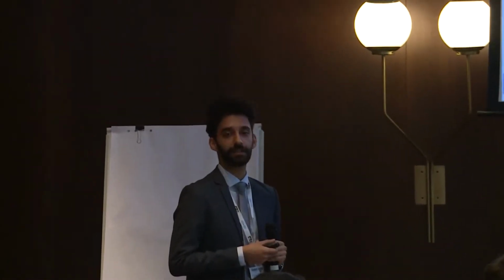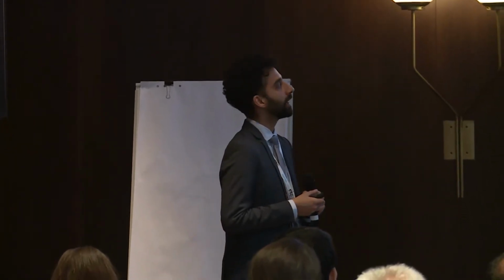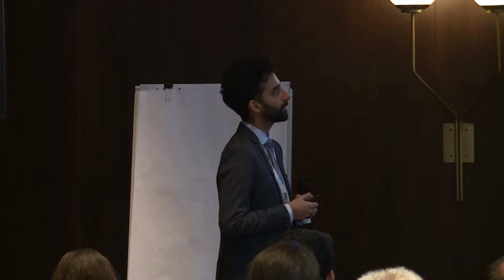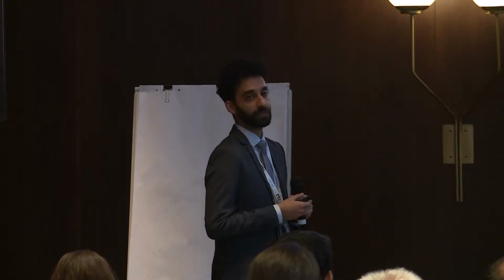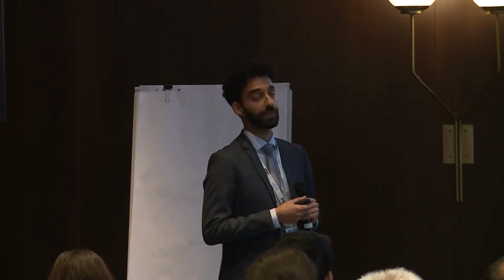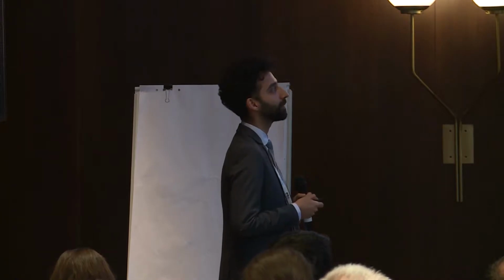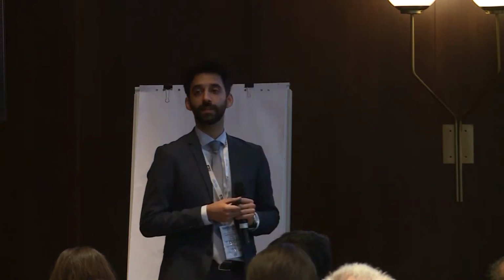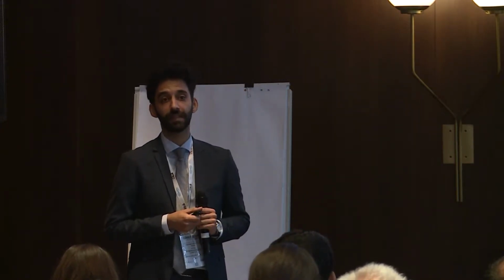If you compare it to the cast sample, here you can see the clear existence of alpha and beta phases, which is quite a different behavior compared to the additive manufactured samples. We are expecting to have more ductile behavior for these cast specimens because the beta phase exists in them.